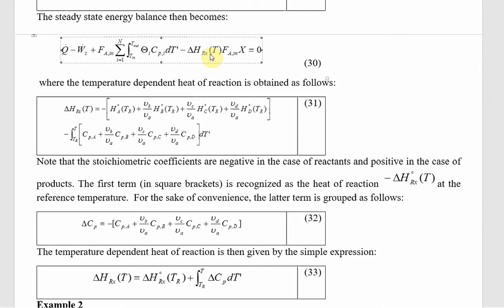And this was the energy difference due to the reaction itself. So due to reaction, we have this heat of reaction times this conversion of component A. And of course, these two terms came just from accounting for the difference in enthalpy between the inlet and the exit. So it's not the case that this balance appeared by saying that in minus out and then plus the heat of reaction contribution. These two terms are, in fact, the difference in enthalpy between the inlet and the exit. Right? Any questions or comments there?